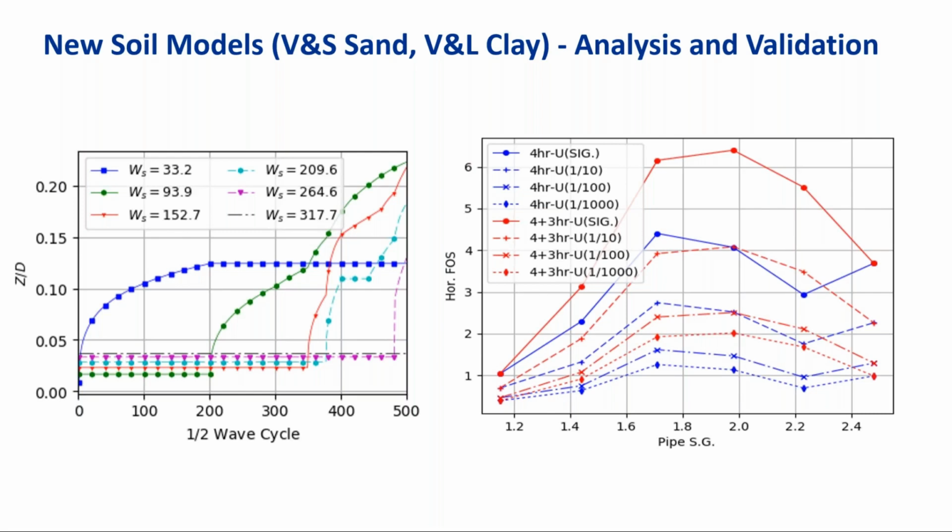And therefore, apparently there is a small reduction in the factor of safety. We had a couple of users asking why, despite increasing their wall thickness or concrete thickness, they don't see improvement in the factor of safety, and that's because sometimes your pipe is too heavy for your environmental conditions. And next one, please.